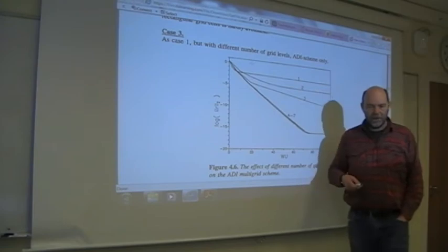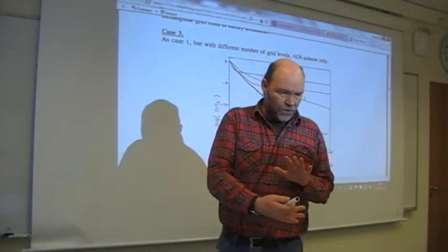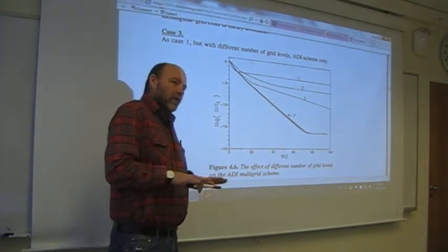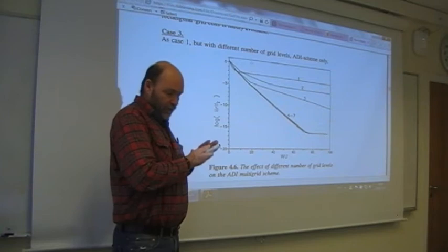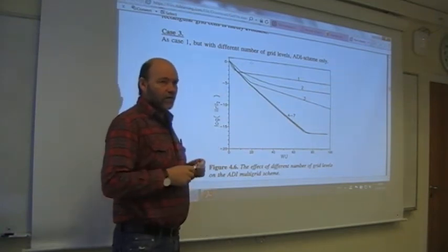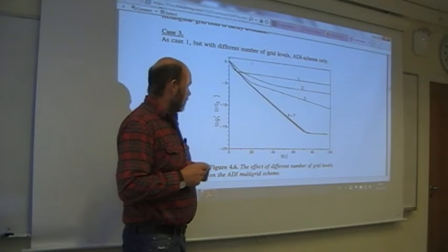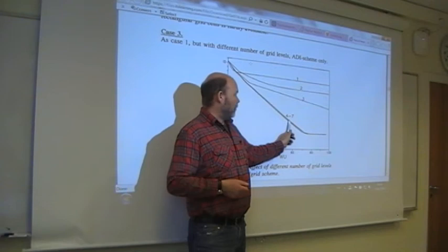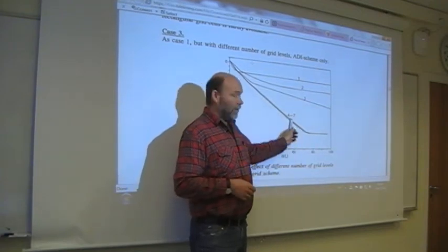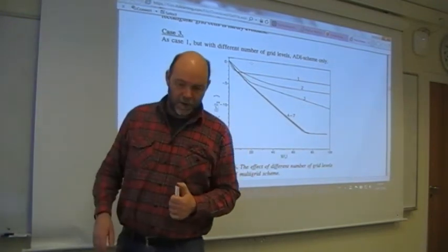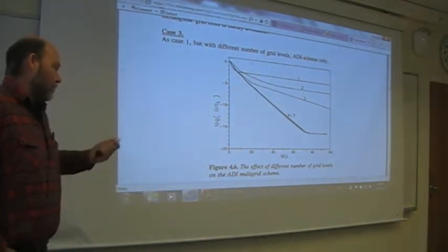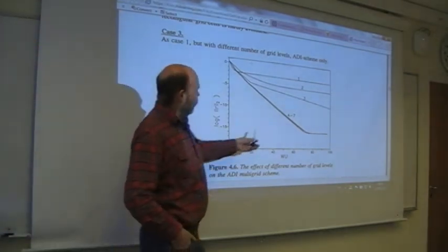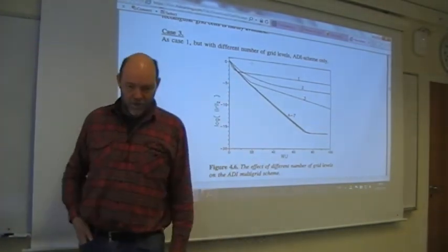So I mean the idea is that when you are on a sub-mesh level, how to find a solution there? Well, you can solve it when you are there directly, or you can still use multi-grid on an even coarser mesh. What's most efficient? So you see from 4 to 7, it really doesn't matter. Of course, when you have multi-grid operating, then this one is fairly easy. You just continue as long as possible. But you could just as well have solved it on the sub-level 4. That will be just as efficient.